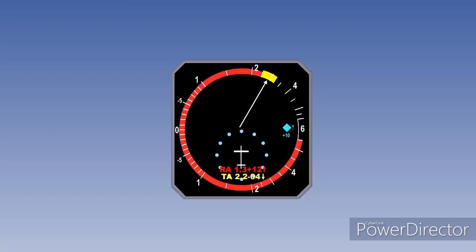The least reliable information displayed from TCAS is the bearing, so crews should not try to interpret tracks or anticipate the system, as they could make the situation worse. This is why all resolution advisories are given in the vertical plane.